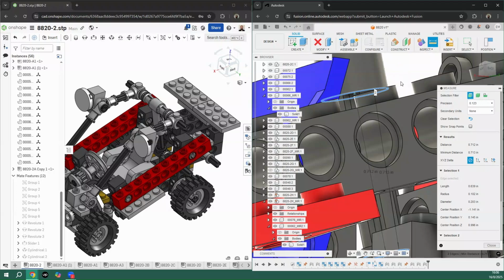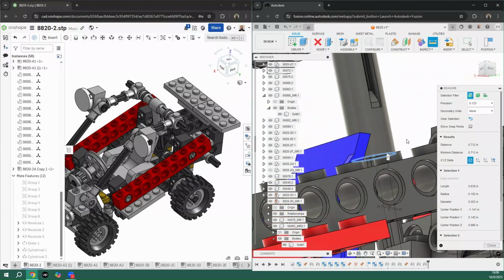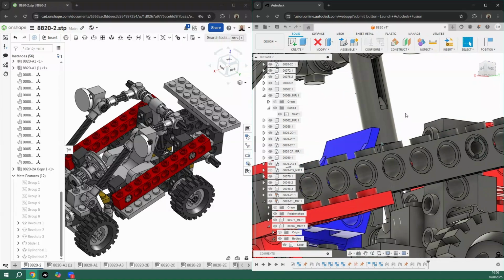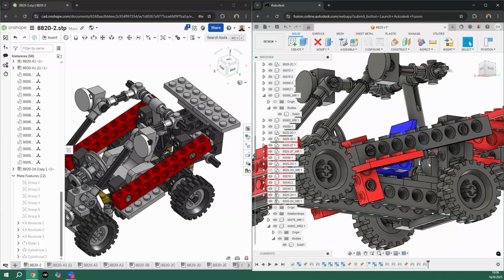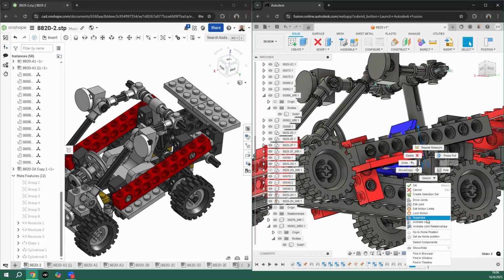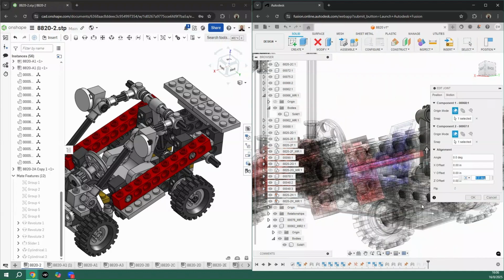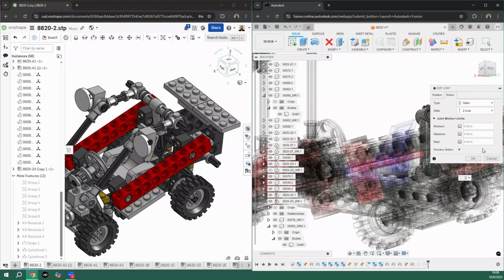Let's say that it can be 0.7 inches. I'm a millimetric guy, to be honest, but yeah, this thing for a reason came as an inches template, I believe. Okay, so I will right-click, edit joint, and I will set my limits right in here.